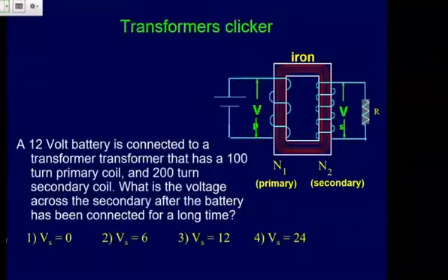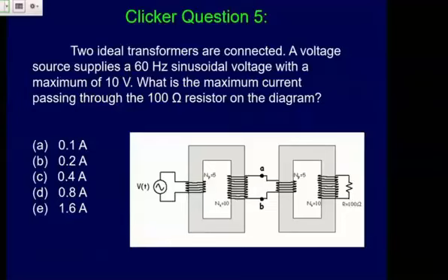That's our general one, so the voltage of the secondary equals the voltage of the primary times Ns over Np. Our initial voltage here was 10 volts, and Ns over Np would be 10 over 5. So we get 20 volts.